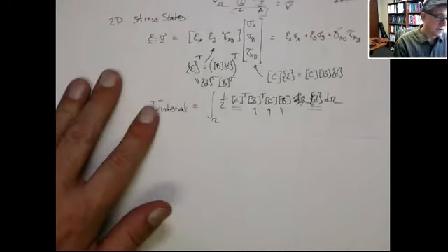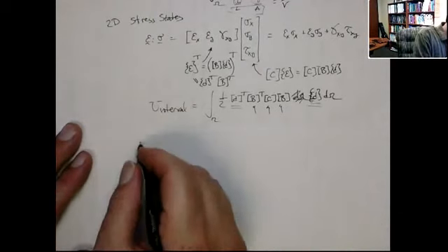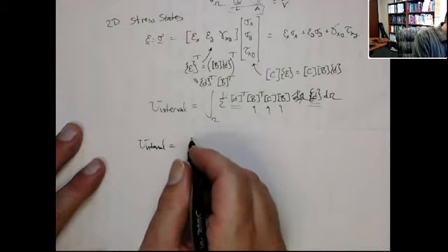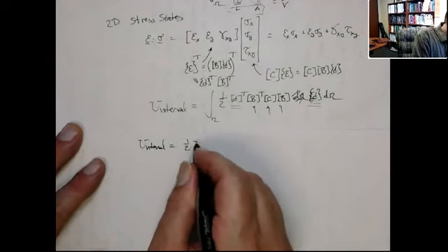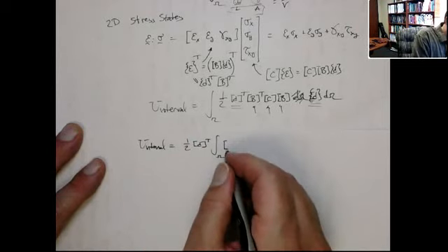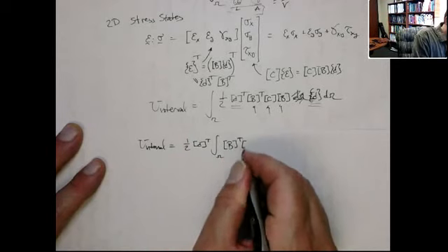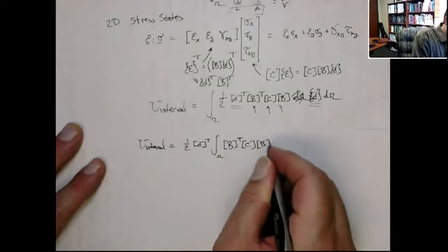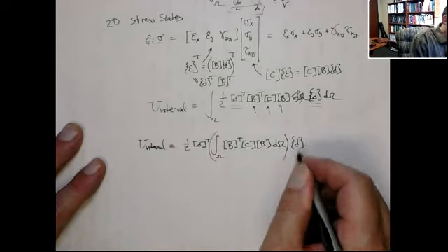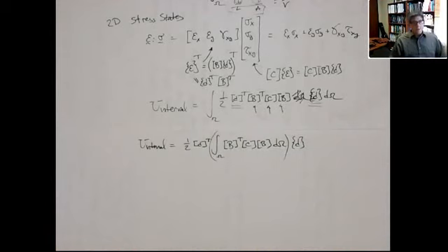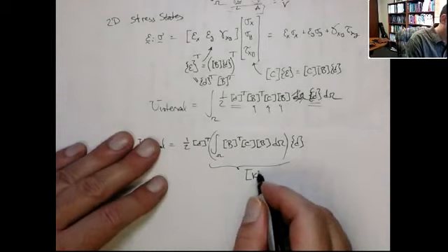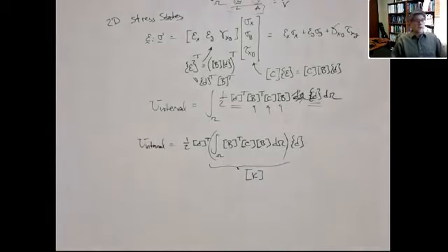And now what do I have? So pulling those things out, I have that the internal strain energy is equal to 1/2 D transpose. Now we're going to integrate over the domain. B transpose times C times B times D omega times D. Okay? This term here is going to turn out to be exactly our stiffness matrix, K.